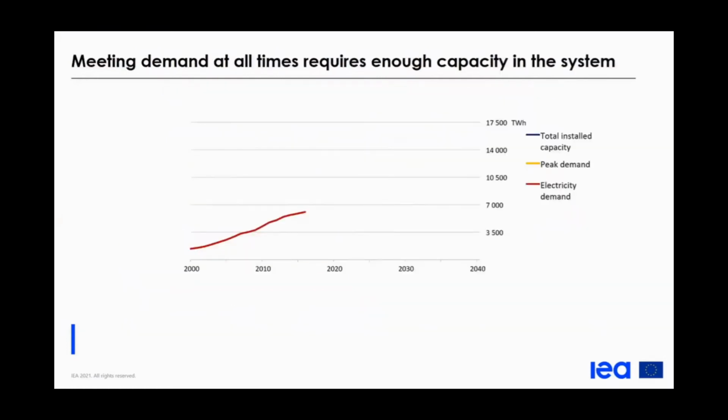Given the evolution of electricity demand over the projection period, the evolution of total dispatchable capacity can be estimated through two steps. First, the peak to average ratio. Remember this 170% above average that we saw in the previous example. We calculate this peak to average ratio based on the analysis of historical data and the evolution of different end uses, for instance, cooling needs or electric vehicles, which can make this demand peakier.